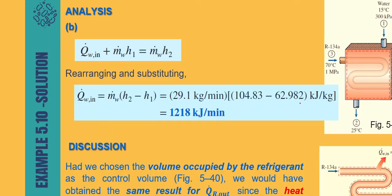If you want to determine the heat transfer, you cannot consider the entire heat exchanger as a system. Instead, you need to select either the refrigerant or the water as your system in order to calculate the heat transfer. This is what is left after you remove all the insignificant terms from the general energy balance equation.